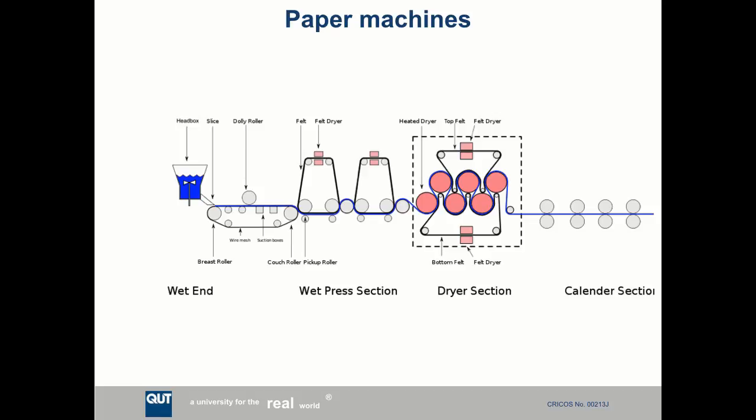A big example in industry is paper machine. Paper machines are big, complicated things. They basically start with this white sludge, which is like very, very dilute paper fibers, like white water, right? And that gets put onto felt, and at the end you want to measure something like the thickness of the paper. And it goes through all these rollers and all sorts of process, but your measurements are quite late, and you actuate right back on the left-hand side. So there's all sorts of delays in the heating control, in the application of the amount of liquid that's being poured onto the felt rolls. All sorts of time delays in this.